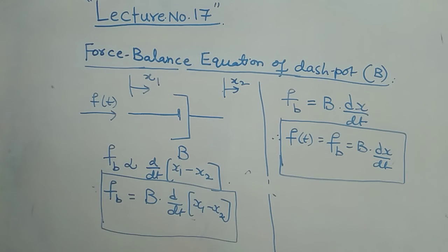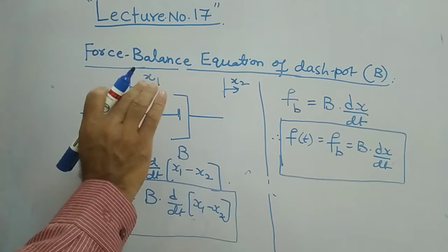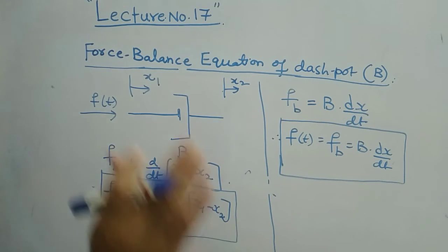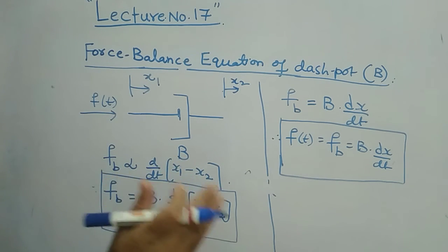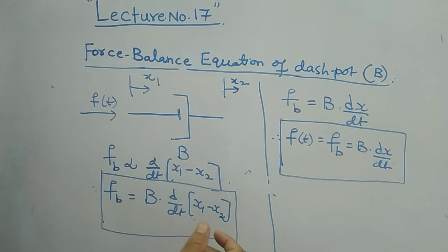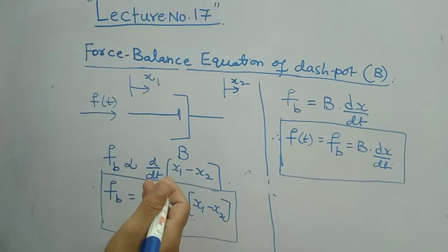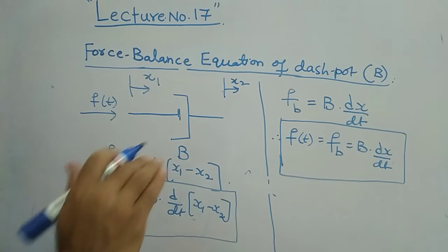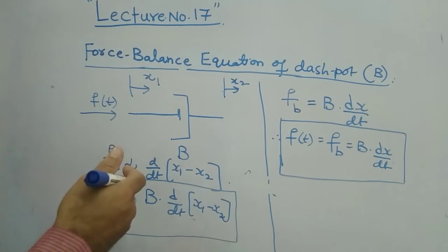There is nothing more. Moreover, for the given problem on this topic, they will ask you to find out the transfer function. So for this mechanical translational system, how do we find the transfer function? Since the beginning of this lecture I have been explaining that the transfer function is the ratio of the Laplace transformation of the output to the Laplace transformation of the input.